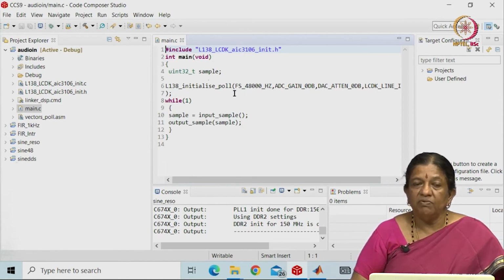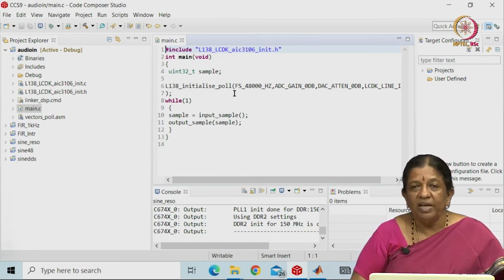Whereas in interrupt driven, as you know, whenever a person comes to your house, they will press the calling bell, and then you will go and attend to that. But if you are expecting a guest, say a chief guest, once in a while you have to go out and check whether the person has come or not. That we call polling, that is, every 5 minutes or so you go and check. If he has come, then you bring him in.